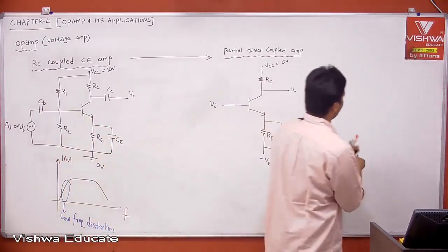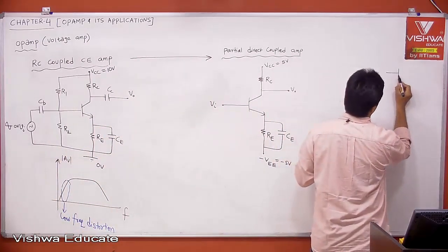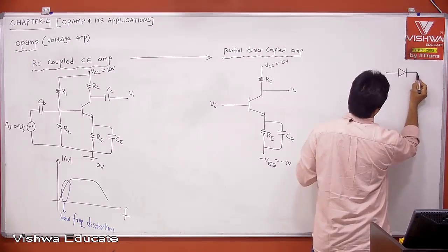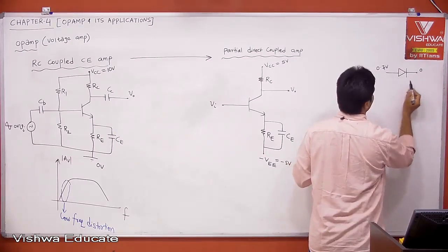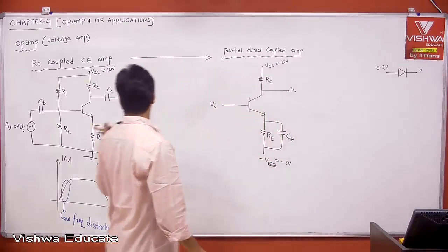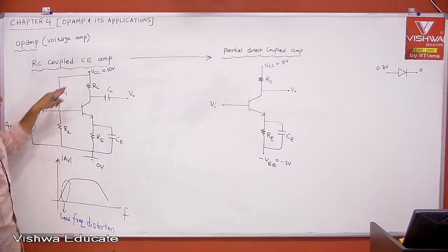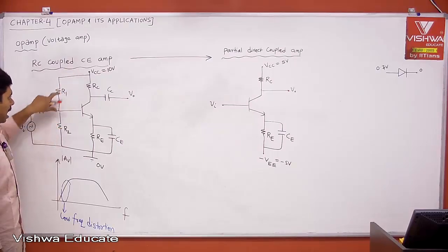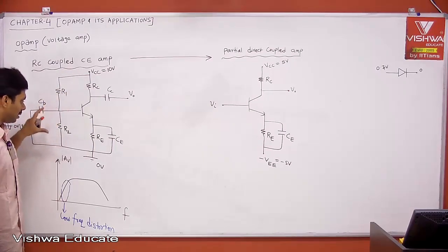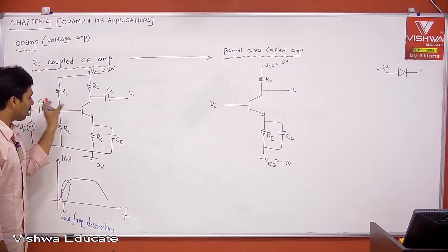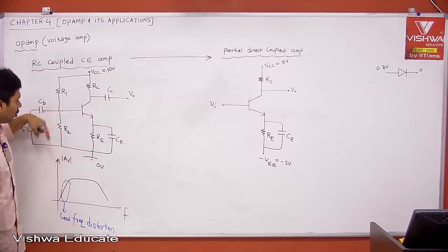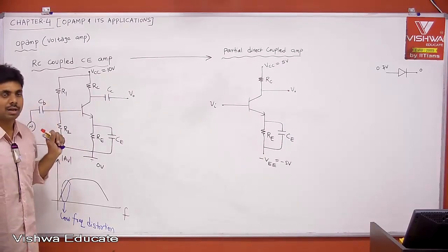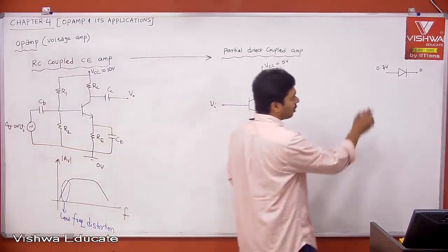If you take a PN junction diode, let us say this is 0.7 and this is 0, the PN junction diode is conducting. That is what we used to do till now. VCC, R1, R2 combination: R2 divided by R1 plus R2 into VCC is VThevenin, and R1 in parallel to R2 is RThevenin. That VThevenin is equal to the drop across RThevenin plus VBE plus IE into RE. We need some voltage to bias our transistor, and therefore we need 0.7.